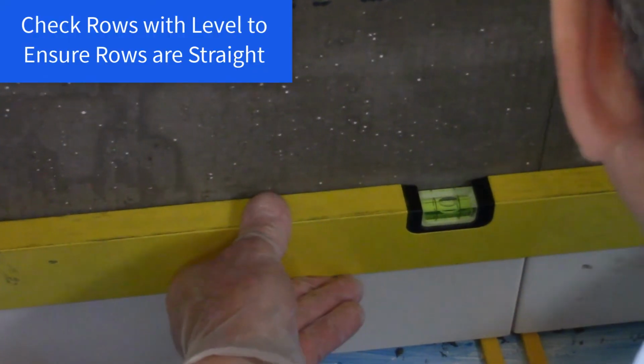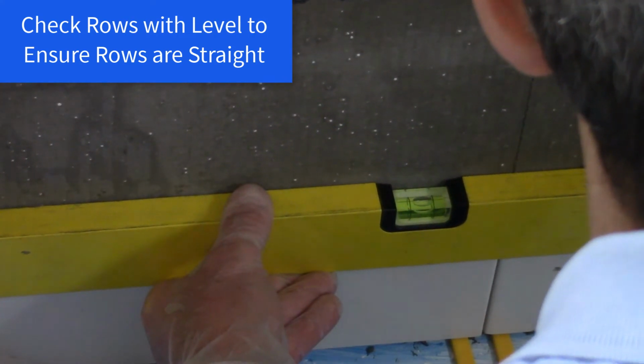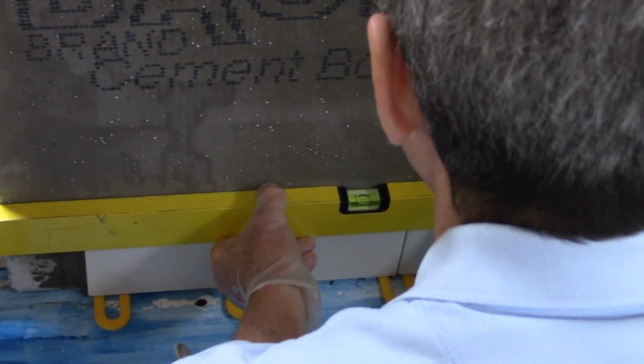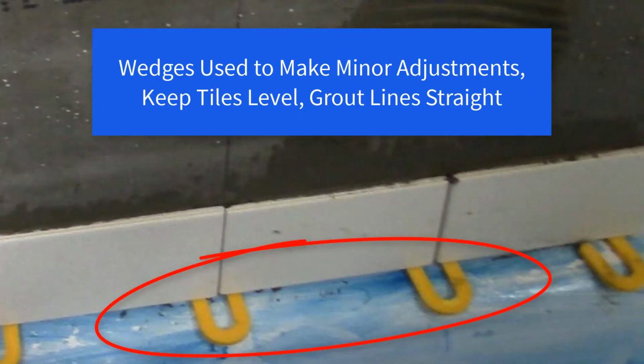Depending on the tile size, check your rows about every 1 to 2 feet with a level to ensure the tiles and grout joints remain straight. This is really important on your first course, as this will be the foundation of how level the tile will be as you tile further up the wall. Wedges can be used at this time to make minor adjustments to keep the tiles level and grout lines straight and equal throughout the installation.